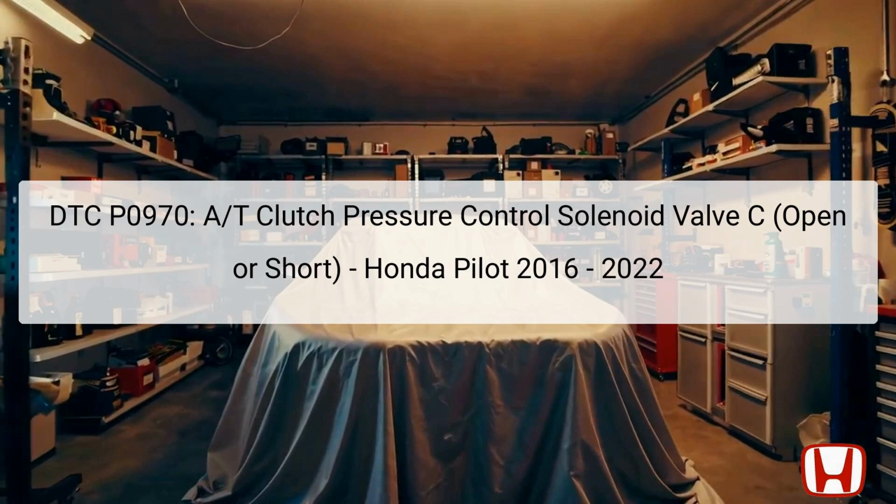The first indication of this DTC is often a failing transmission that may only shift into first, second, or fifth gears due to a fail-safe function embedded in the powertrain control module, PCM. This safety feature prevents further potential damage to the transmission system.